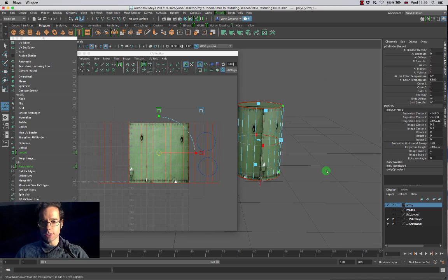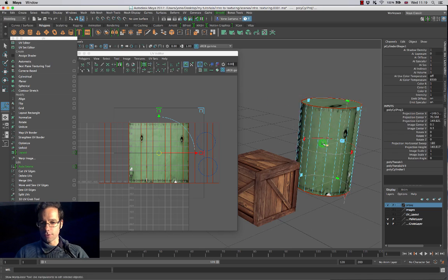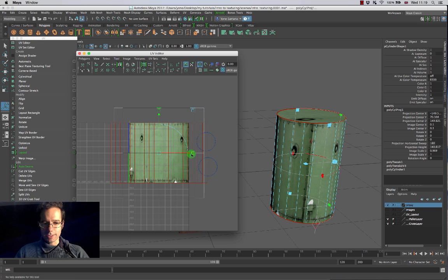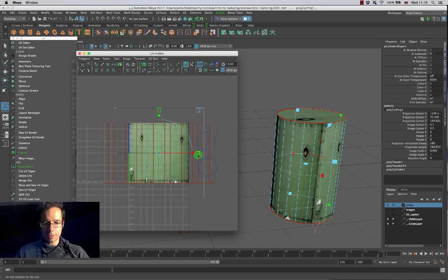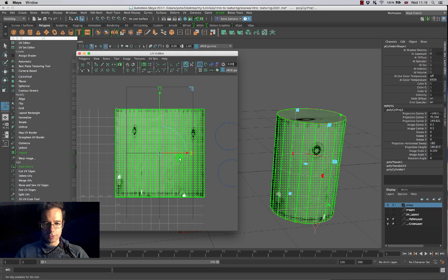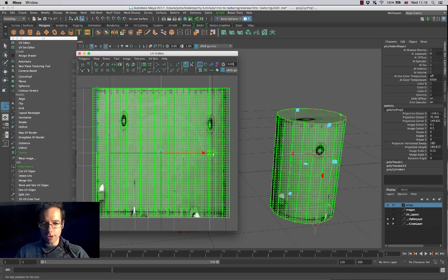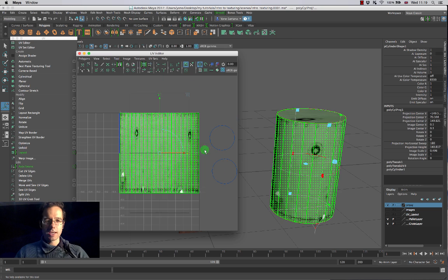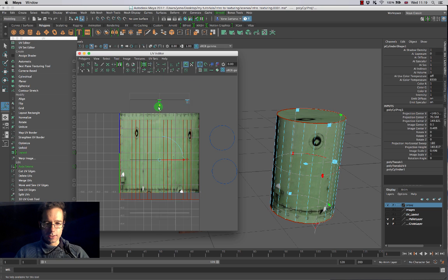You'll also see a 3D version of it inside of here as well. So you should see these little axes over here. If I grab these little squares at the end, you're going to see that these work very much like the scale tool inside of the extrude tool or inside of the regular scale tool as well. If I drag these handles, I can do a scale in the x-axis, and if I wanted to, I could do a scale in the y-axis.